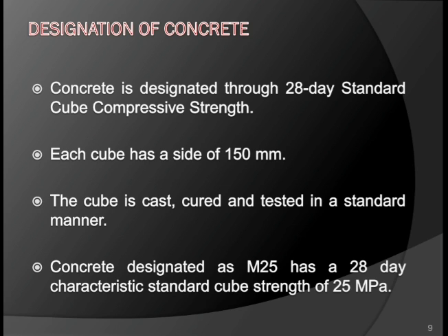The cube is cast, cured and tested in a compression testing machine, and the concrete designated as M25 has a 28 day characteristic standard cube strength of 25 megapascal.